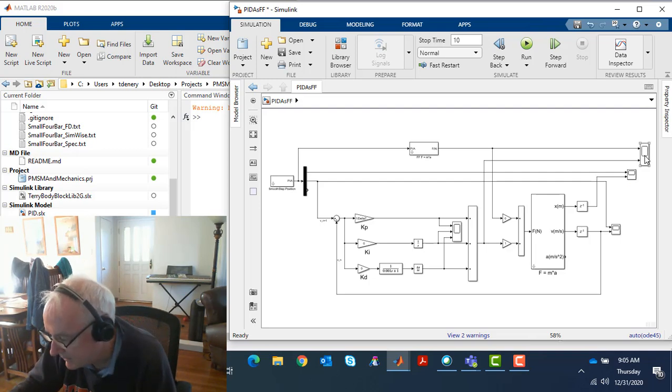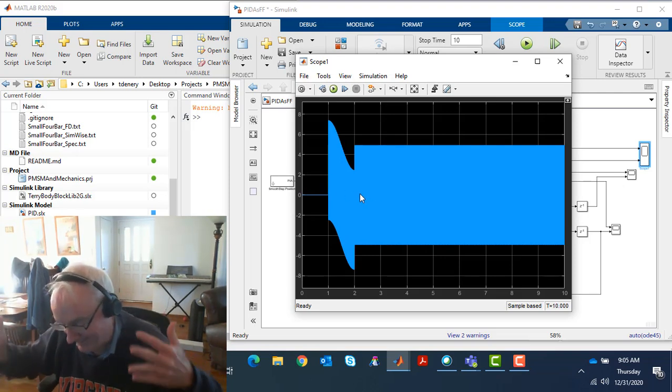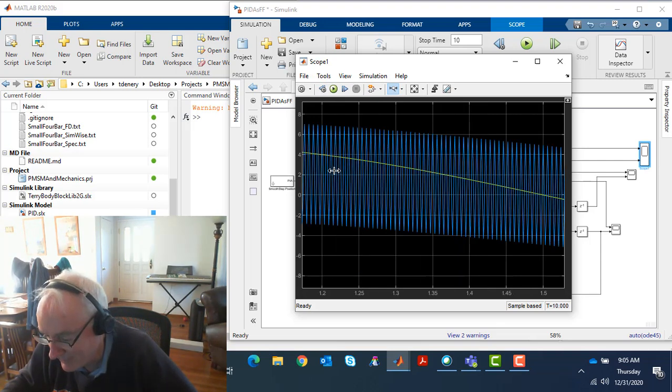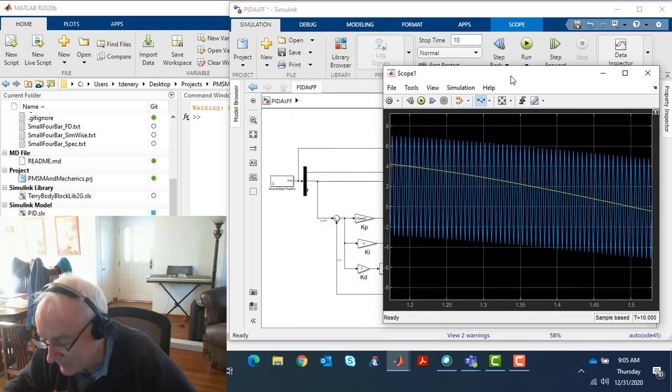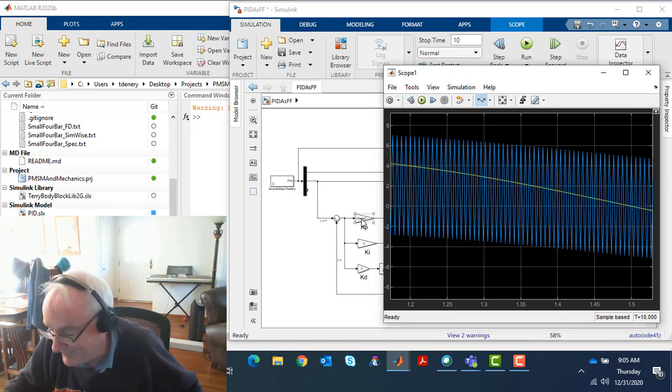And let's see. I guess I'll show this next. All right. But this is really important. Okay. And there's a few things to talk about here. And I certainly don't want to argue that a good controls engineer would allow this to happen. Okay. But, in the previous, well, let me say this. Our time step is 1/1000th of a second. So that means our gain is equal to 1,000. And we saw in the previous video that we got pretty good control with a proportional gain of 100. So this is a really, really high gain actually for this system.